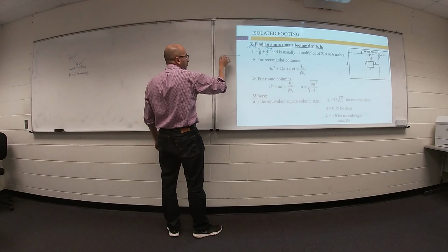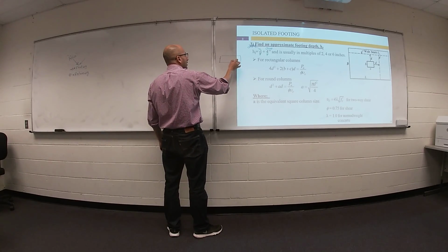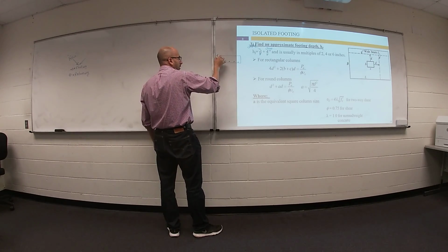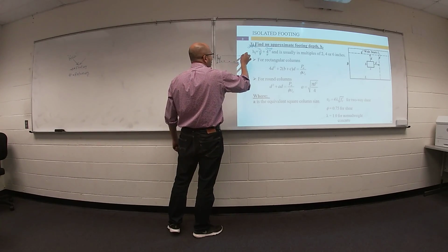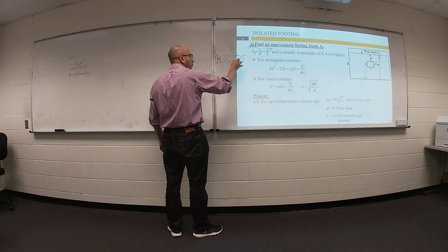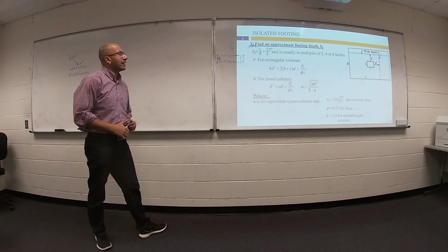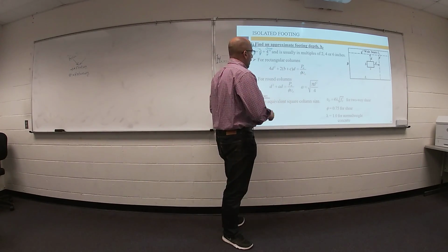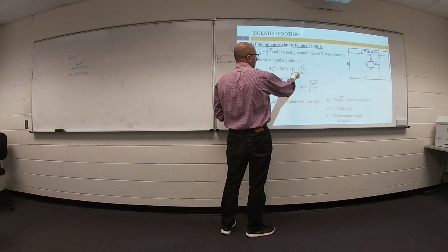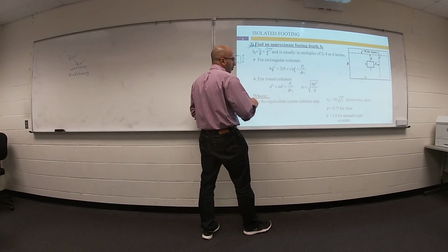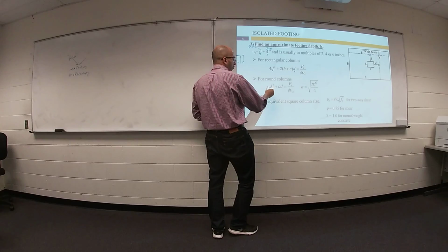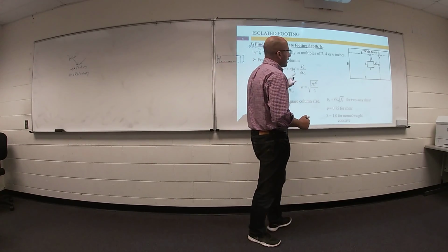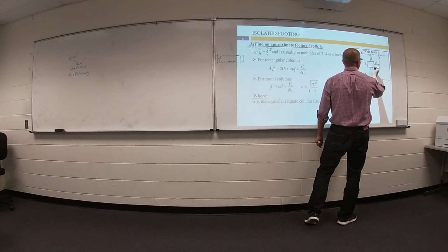and just for your information, here is your steel reinforcement. HF is the total thickness. D is the depth, so the distance between the top to the center line of your reinforcement. If your column is rectangular, we can use this equation to figure out the value of D. If your column is a circular column, we can use this equation to figure out the value of D. Just for your information, B and C are dimensions of the column.